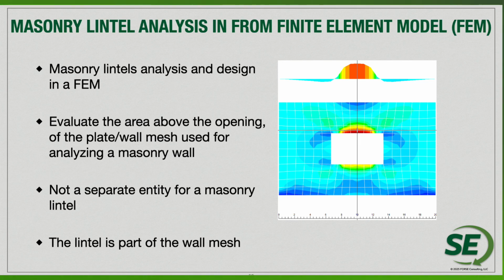Certainly, again, the finite element analysis is going to be necessary. Looking at the lintel is going to have a lot of contribution in the in-plane direction. You're going to have load reversals for your in-plane shear if it's going to be a reversing in-plane load. A lot of wind load, seismic loads, obviously you're going to operate in both directions. So recognizing that you have positive, negative forces at the top and the bottom of the lintel areas. Certainly, again, a finite element analysis can help you determine what those forces are going to be for that area above the opening so that we can get a proper lintel design.